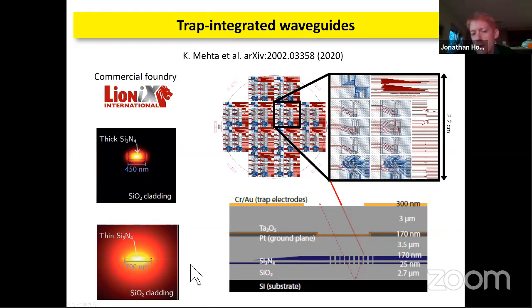Well, because to come from the chip, then we have an optical fiber, and what we can now do is we can basically butt couple it up to the edge of the chip and glue it. Yeah. And then there's an adiabatic taper, which takes us between that edge region and the guiding modes, which are meant to take the light to near the ions. And that allows a good transfer of light from initially a fiber guided mode all the way to where we want them, which is near these gratings, which are going to diffract the light to the ion.